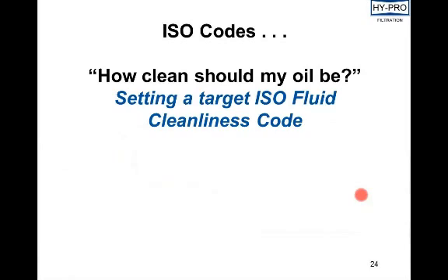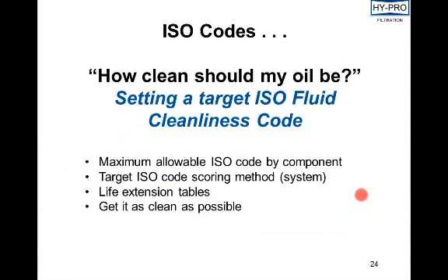So we have a little bit of discussion on target ISO code. How clean should my oil be? Different ways to look at that. You can identify the most sensitive component on the system, let's say a servo valve, and set your target fluid cleanliness accordingly to that.